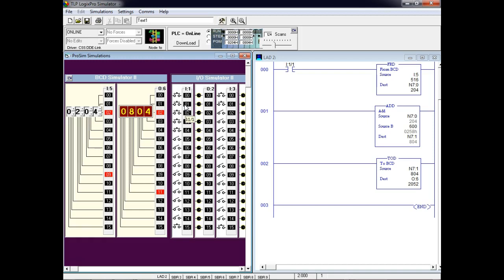I thought you said no, this is a BCD display. This is a BCD display because I don't understand F's, A's, and C's, right? So normally when you look at a numerical display on a PLC, it doesn't give you binary, it doesn't give you hexadecimal, it gives you what? It gives you BCD, it gives you decimal, but we have to represent that as a code of ones and zeros. And that code we call BCD. You don't even know BCD. All you know is 804. An operator doesn't care how the 804 got up there.